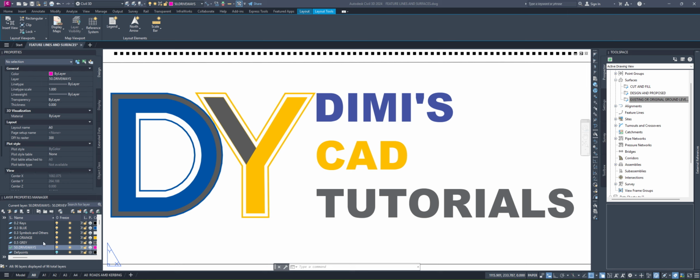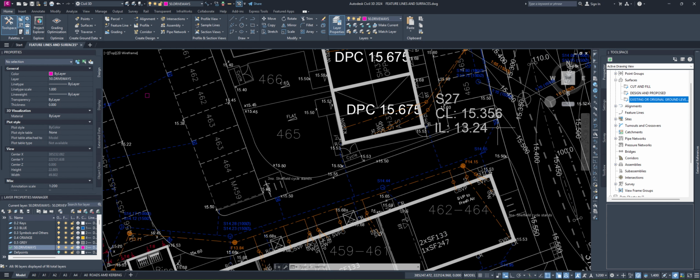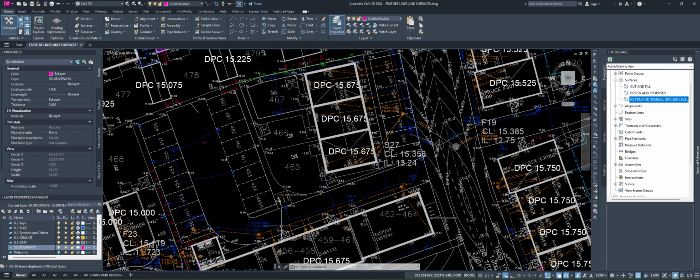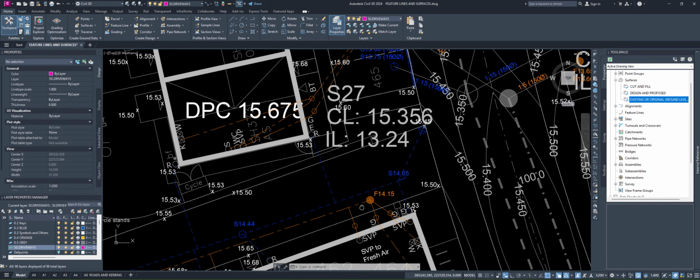But first, I already created my layer. I advise you to create exactly the same, create a layer and make it current. Then we start chasing our model, let's call it a shared drive for a model. We're going to chase all the edge lines, all the channel lines, all the way around with the polyline until we come to the end and completely loop our model. Our polyline is going to be completely closed.